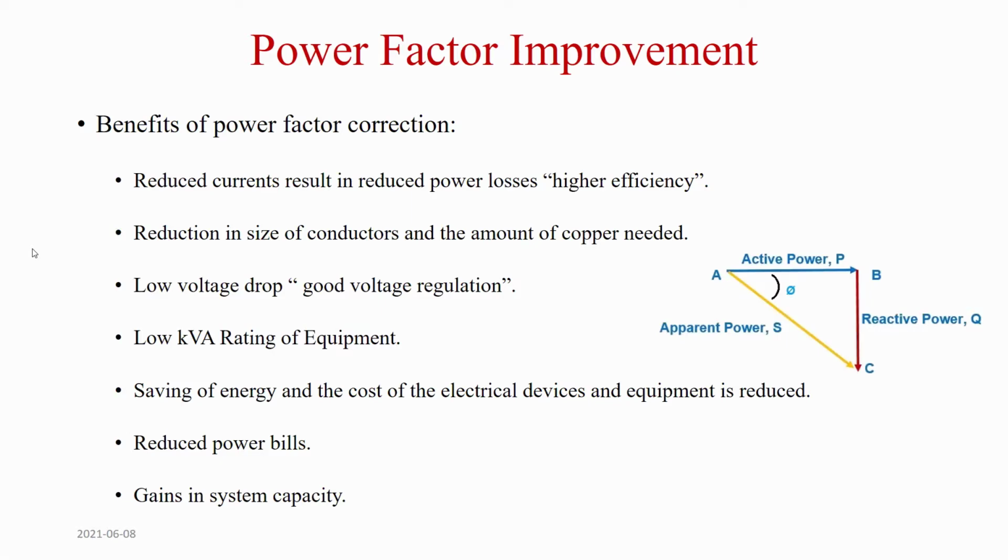So when we improve the power factor, what do we get? We reduce the current. That reduces the power losses. That increases the efficiency. That reduces the size of the conductors. That reduces the money that you need, okay?